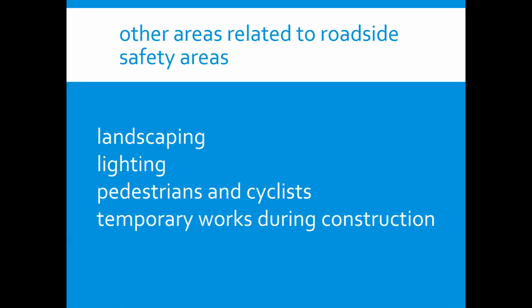It is recommended that trees with small trunk diameters less than 100 millimeters should be used for medians and borders, while for traffic islands, lower level vegetation or trees with higher canopies are appropriate. Provision for adequate sight distance for all road users must be considered, as mentioned throughout my lectures and as shown on my slides. The designer must consider the balance between the streetscape and a road safety objective.